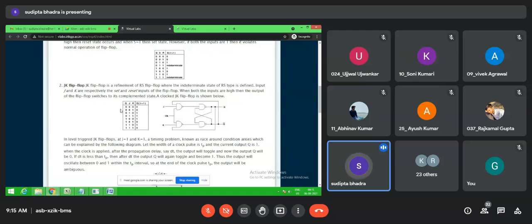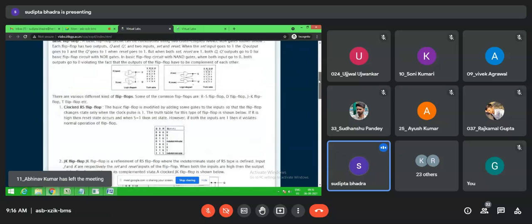So here you can see in the truth table for JK, for 1 1, for 0 state and 1 state where the Q is either 0 or 1, the Q(t+1) is correctly determined. When it is 0, Q(t+1) is 1. When it is 1, Q(t+1) is 0. So the problem of this intermediate state of SR is overcome by the JK flip-flop.